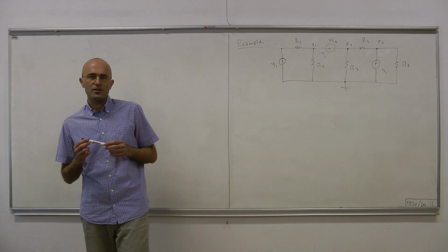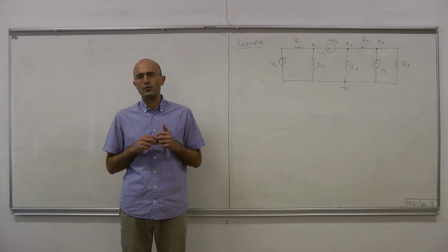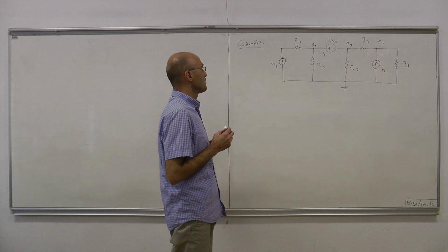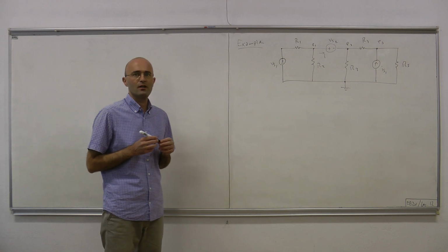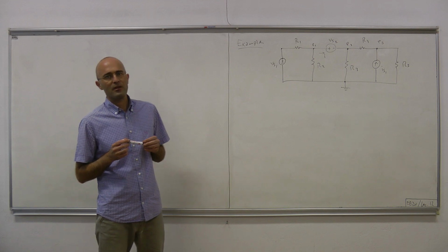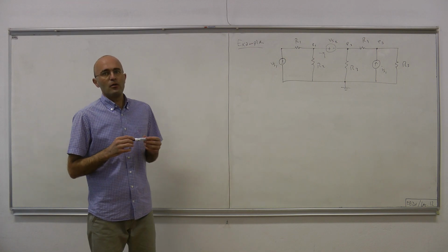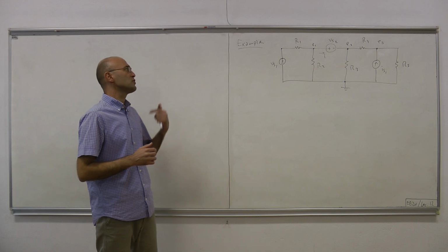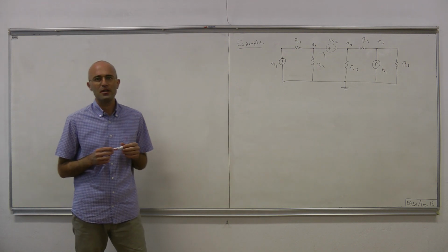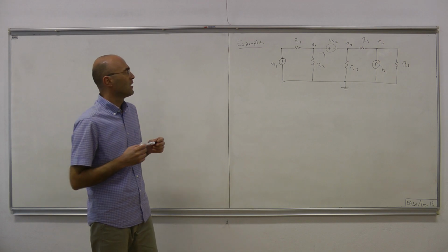In our previous lecture, we started talking about formulating linear time invariant resistive circuits in order to be able to solve them. And the first approach we talked about last time was called the node voltage analysis, and the idea was very simple. It was that you formulate the circuit in terms of node voltages, by which we mean you write at each node equations imposed on the circuit by KCL in terms of node voltages.